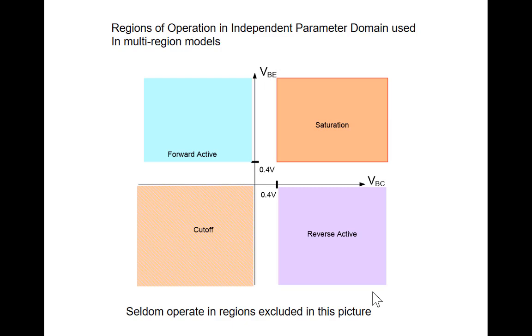Yeah. You get amps or tens of amps or hundreds of amps or kiloamps of current flowing. So you get monstrous currents and big voltages, and you get watts or tens of watts or hundreds of watts or kilowatts or tens of kilowatts of power dissipation. And immediately the device will destroy itself. Okay? So when does that happen? When both junctions are forward biased. So you get very, very far up in here. Don't have to worry about modeling it because the device will destroy itself.